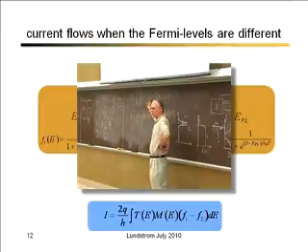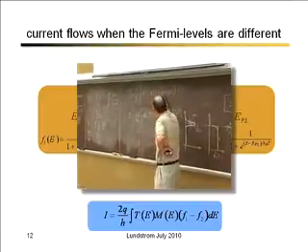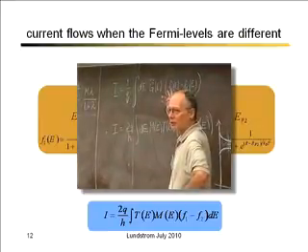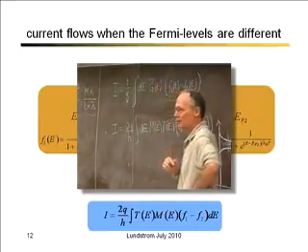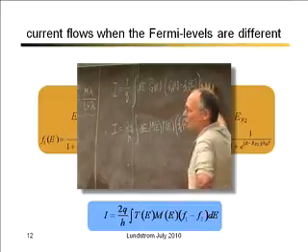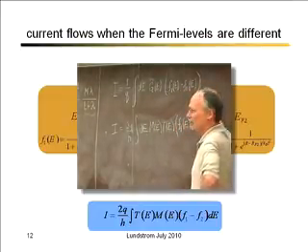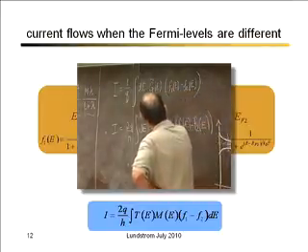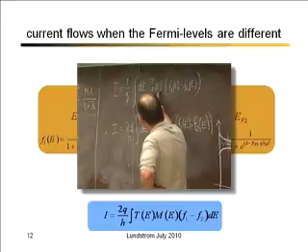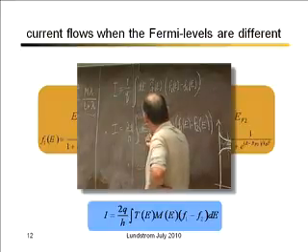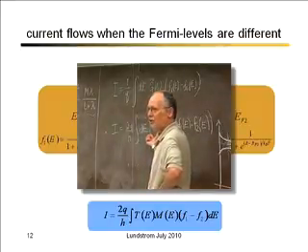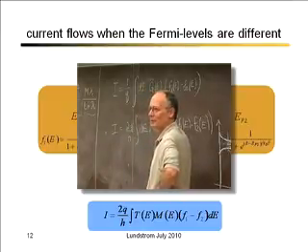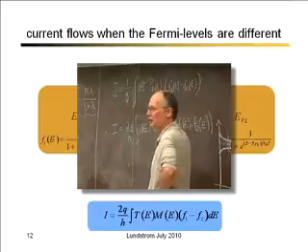There was an energy resolved conductance that he discussed. And what's important is that current only flows when there's a difference in Fermi level between the source Fermi level and the drain Fermi level. So I'm going to write this expression in a slightly different way. It's another way that people commonly use. We're going to write this energy resolved conductance as the product of M, which is a dimensionless number, the number of conducting channels, and transmission, which is another dimensionless number between 0 and 1.